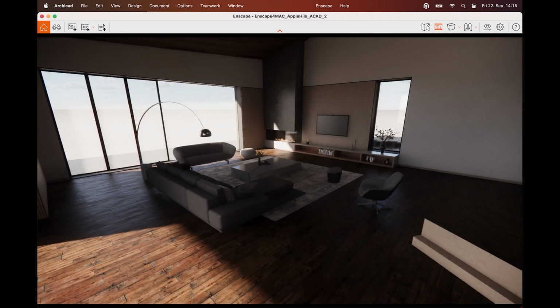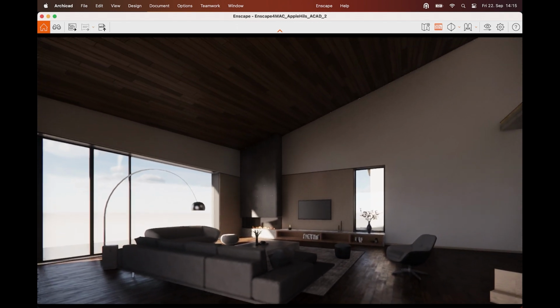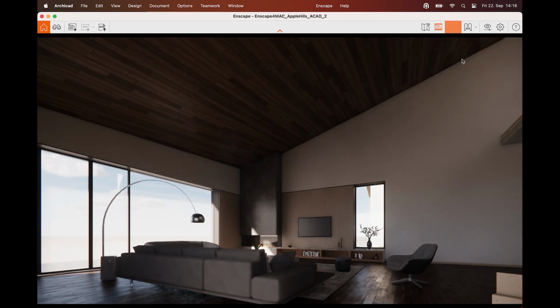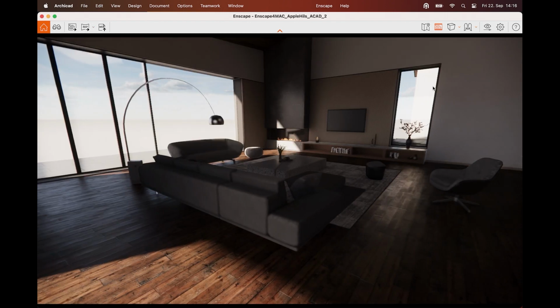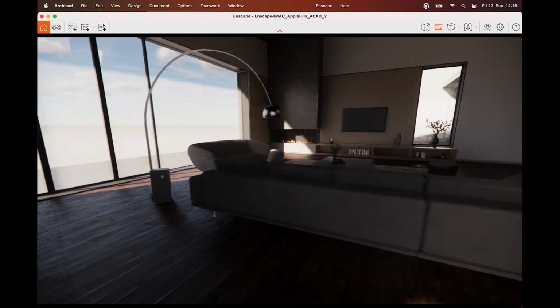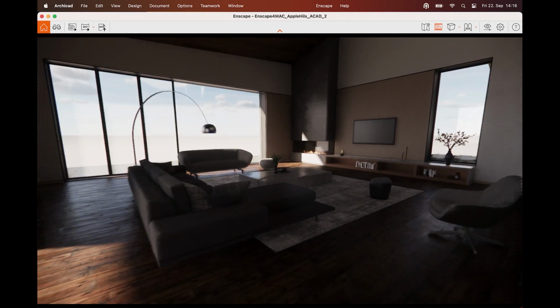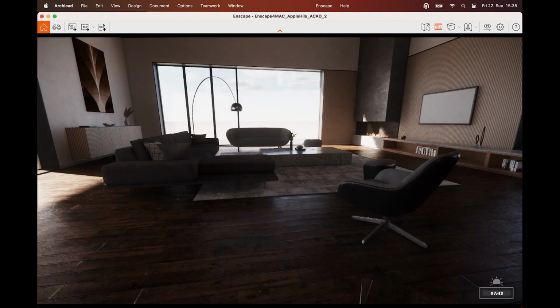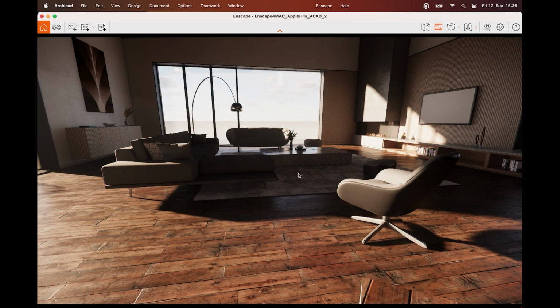Alternative types of perspective include a 2-point perspective, and an orthographic perspective. But let's stick with a default perspective for now. Adjust your position accordingly. Lastly, let's use Shift and the right mouse button to change the daytime so the sunlight or artificial light, if you choose night, play an interesting role in the picture before hitting export.